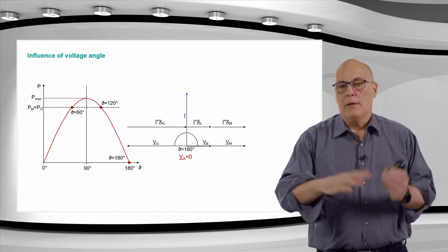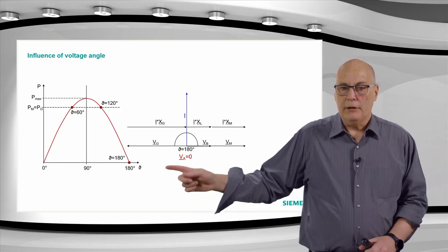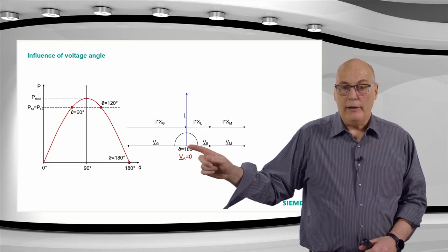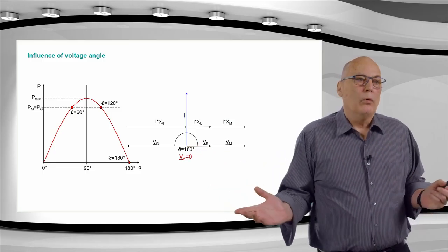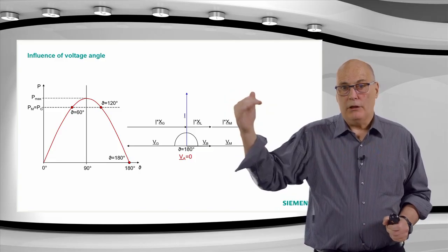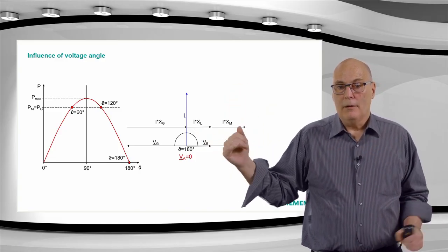That's where the systems have turned completely open. It's very interesting in terms of our distance protection. You can see here what happens at our relay A, the voltage is now 0. What will the impedance be? The impedance will also be 0. Remember, impedance is voltage divided by current. No matter what the current is, the current will not be 0.